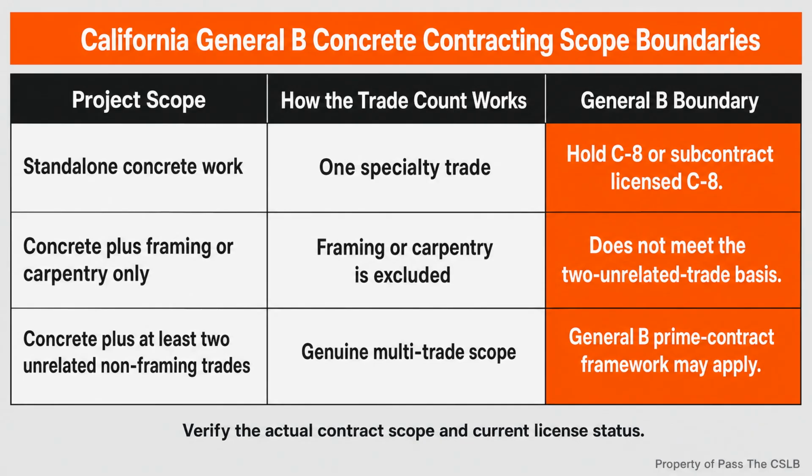That changes what the superintendent must protect in the schedule. If the spray angle is poor around congested reinforcing steel, material can bridge across the face of the bars and leave hidden voids behind them. The source material describes that condition as shadowing. If the material reaches the surface with inadequate, useful velocity, compaction can suffer and rebound can increase. The visible face can look finished, while the concealed condition behind the reinforcement is not sound. That is the central why in this episode.